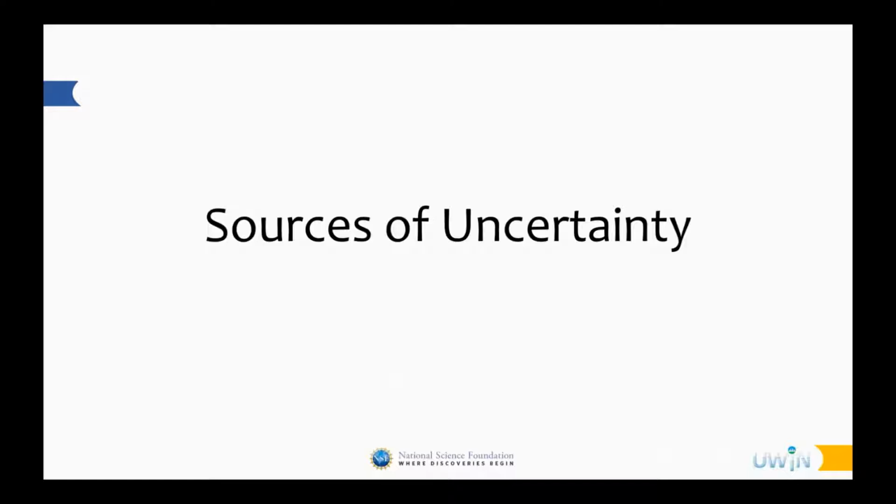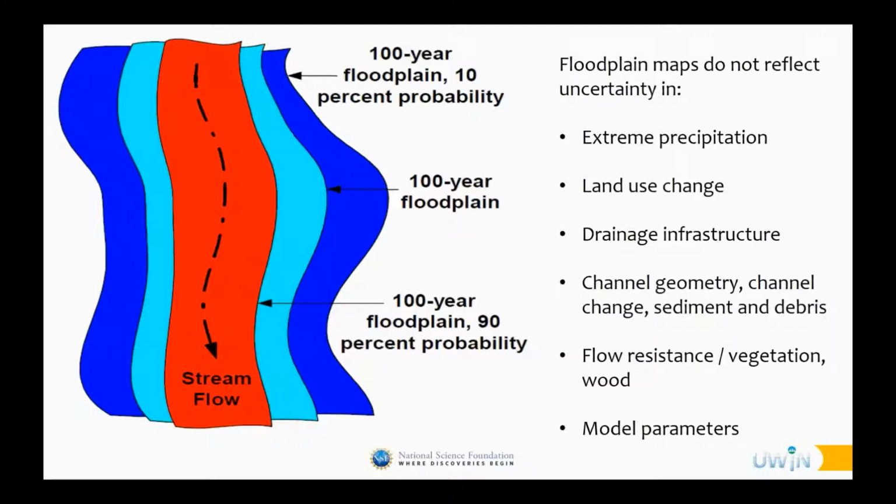So let's explore some sources of uncertainty in flood inundation mapping. A quick list of things to consider would be uncertainty in what's happening with extreme precipitation. For example, here in the southeast U.S., we're seeing some evidence of shifting seasonality and intensity of rainfall where maybe mean annual precipitation is roughly bouncing around the same mean, but it appears that we are having some more intense, hard-hitting events in some cases, and of course rapid urbanization, especially along the I-85 corridor connecting Atlanta and Charlotte.